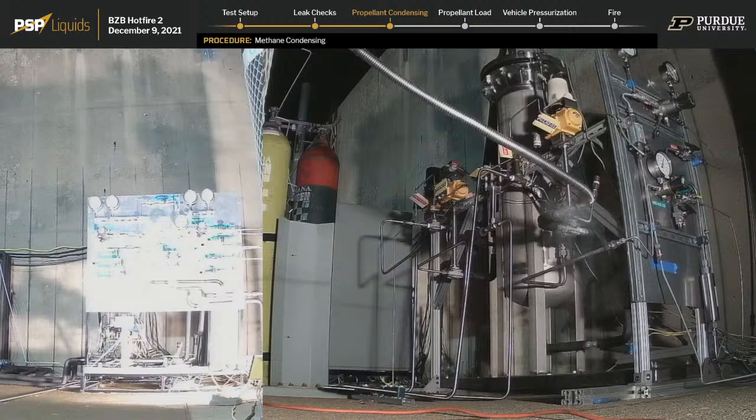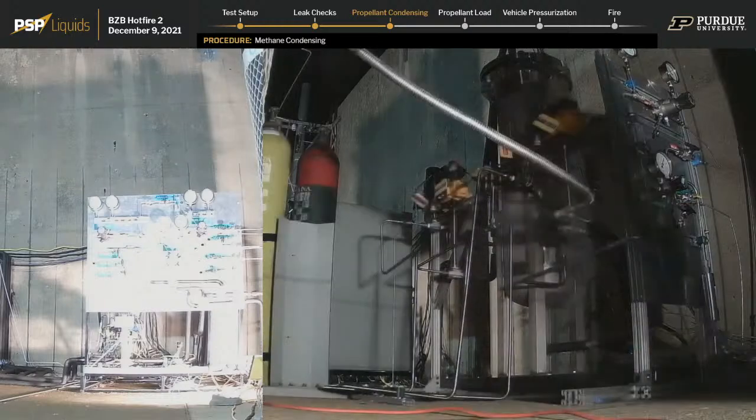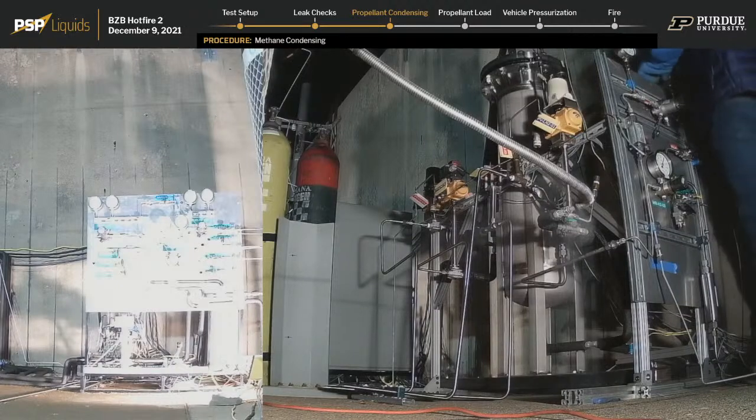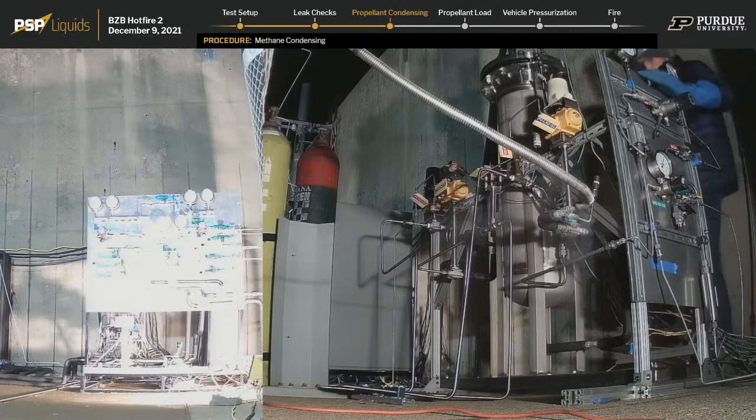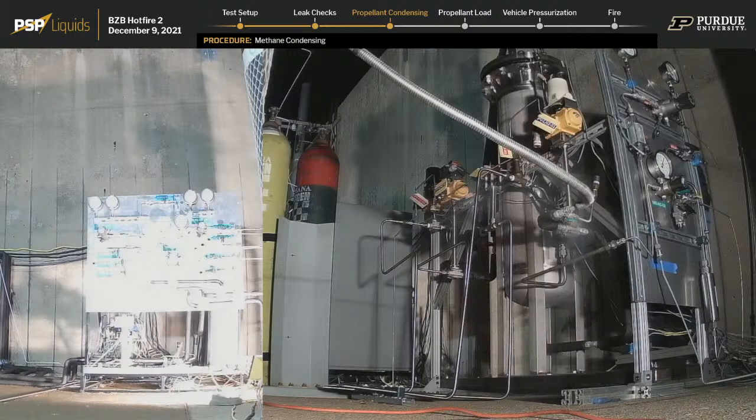We just had vapor coming out as LN2 vent. I think. Do you think the dump valve's open? Yeah. I think the dump valve's open. We're gonna double check it, over. We believe that sound is the liquid nitrogen venting. And as you just heard the call out, not exactly intentional. Yeah, the LN2 dump valve was open. We should add procedures to verify that. Over.